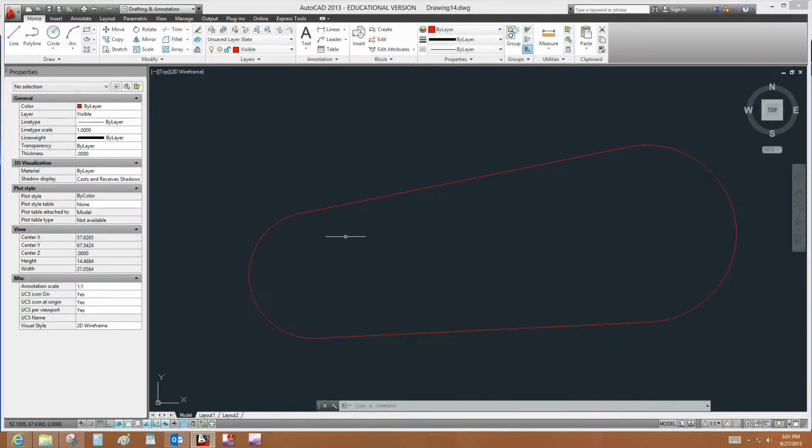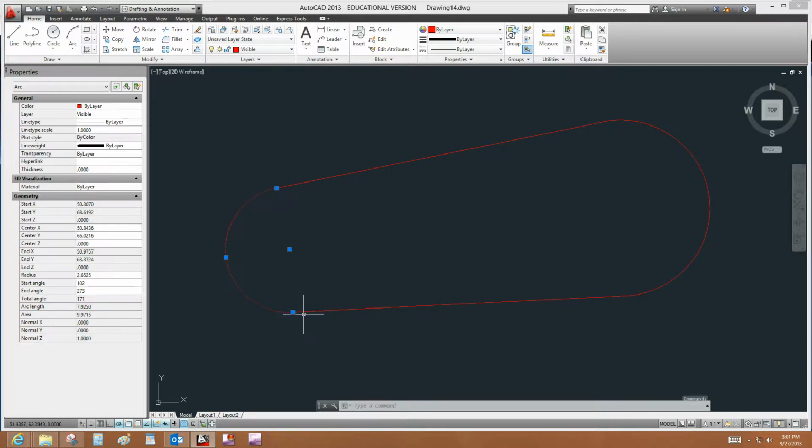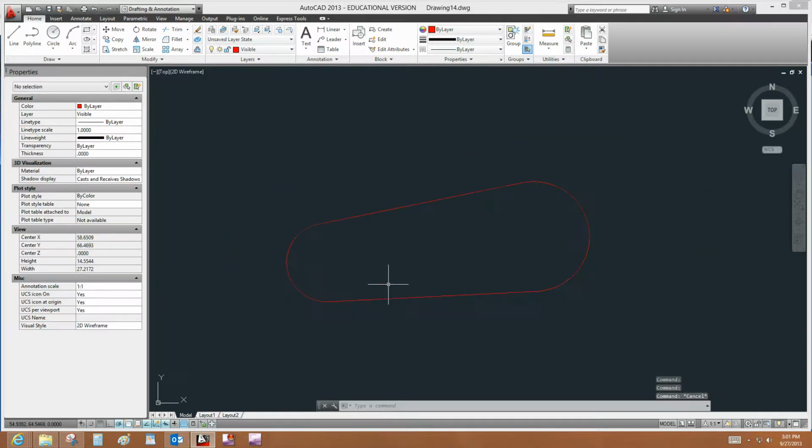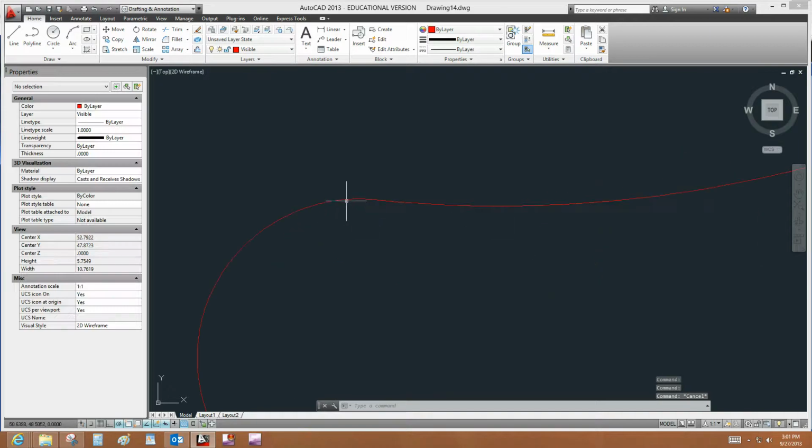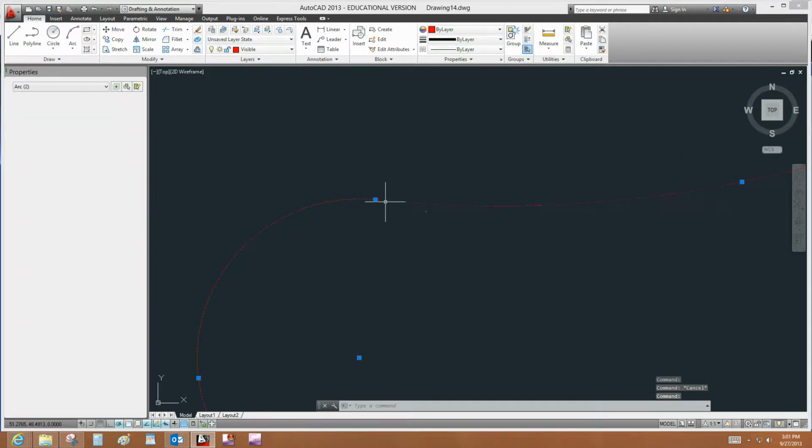If the line were connected to any other place than the tangent, you would see it like a jagged edge there, okay? And that's something you need to recognize when you're looking at drawings, okay? And all four tangent points on this drawing have a smooth transition. And then you see this same thing can happen from arc to arc, okay? So there are four arcs here, and they are tangent to one another, okay? There's a smooth transition from arc to arc.